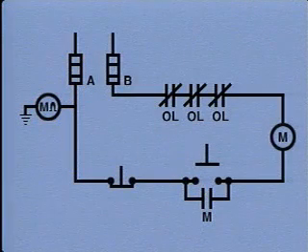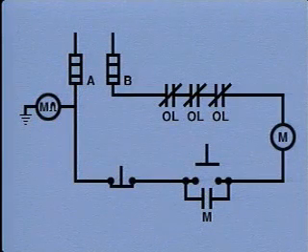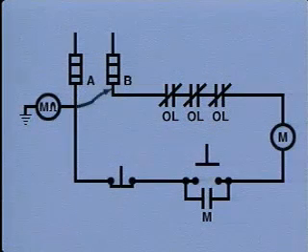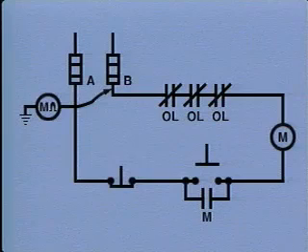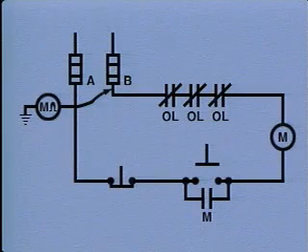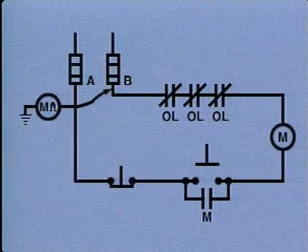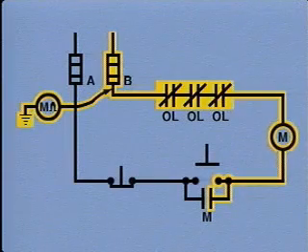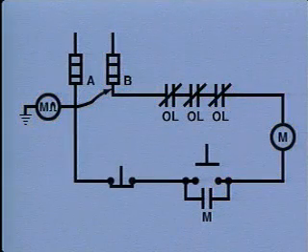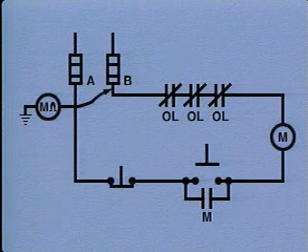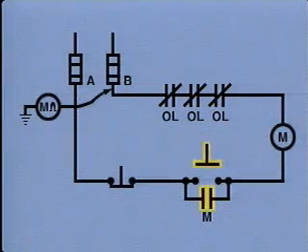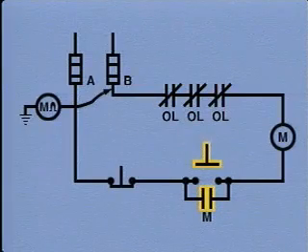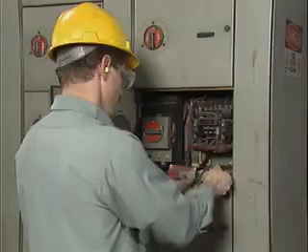In this case, the megohmmeter indicates a high reading, so there is no ground here. To check the remaining portion of the circuit for grounds, the megohmmeter test lead that's attached to ground is left in place, and the other test lead is moved from fuse A to fuse B. Again, the megohmmeter's reading indicates a high reading, so there is no ground in this portion of the circuit either. In this example, these two tests for grounds are enough to cover the entire control circuit because the circuit is divided into two parts by the open start button and its open maintaining contacts.